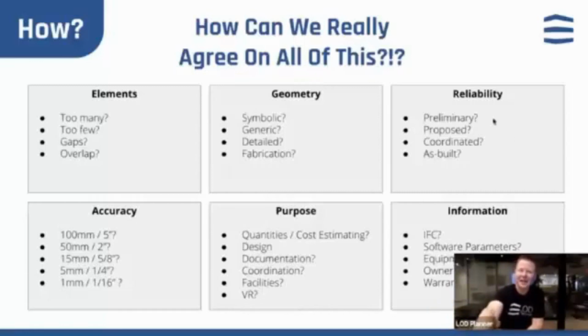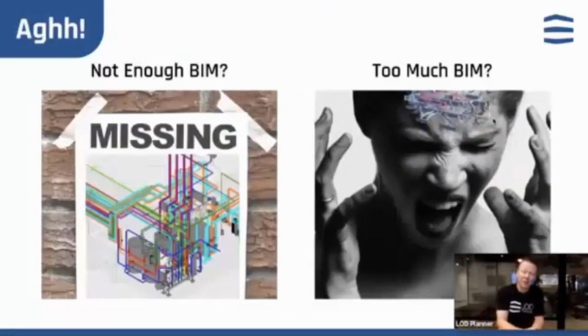It's really tough. And unfortunately, what happens if you haven't got those things in place is we end up having missing BIM, where sometimes you are halfway through a project and you realize that nobody modeled the light fitting. Or you end up with too much BIM, and it could be that you have 7 different people that modeled the light fitting. It might be the architect modeled it early on, the owner had their own object that they wanted to use, maybe the interior designer also modeled it, maybe the electrical engineer, and maybe the contractor. They all created a light fixture, and that's too much BIM. So you can go from either end, where you either have not enough, where you missed scope and you have scope gaps in the model, or you can go all the way to the other side and have more than one person doing the same thing, which is waste.